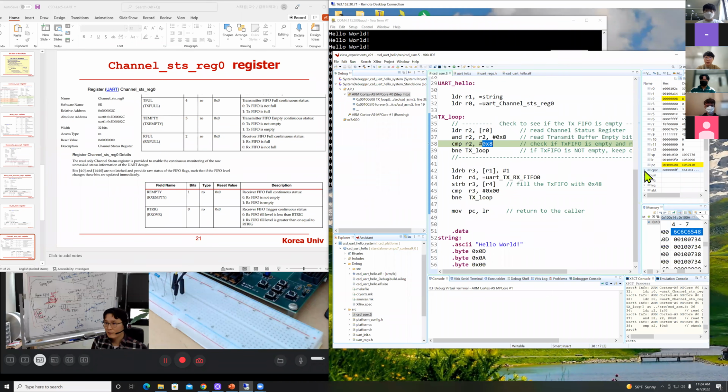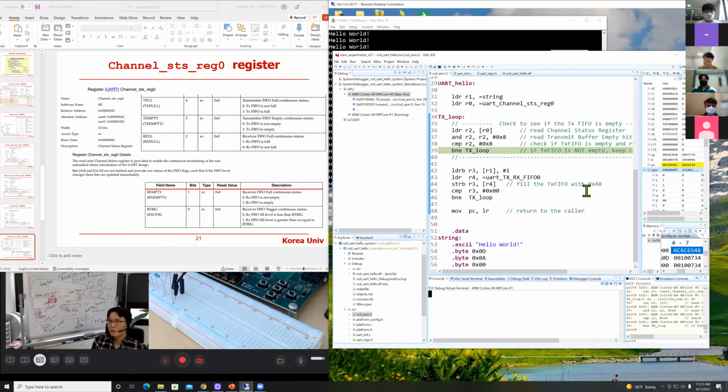Then like this, CPSR, right? The compare instruction is updating the CPSR register. These two are equal, so the zero flag and carry flag will be set. But we are not using the carry flag in this case. We want to check only the zero flag, right? These two are equal. Look at this. Let me check. So no change. Already 1 1, so probably no change. No change in flags.